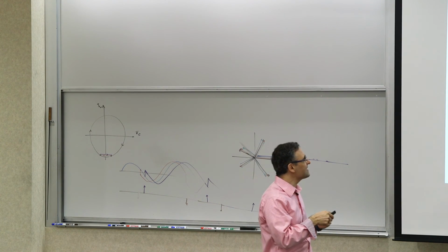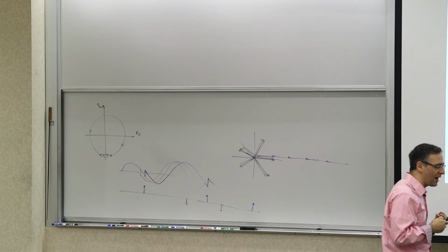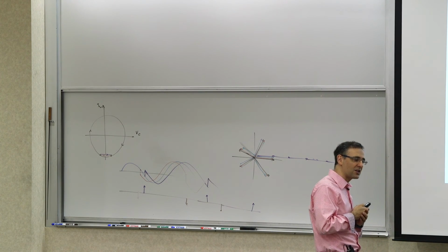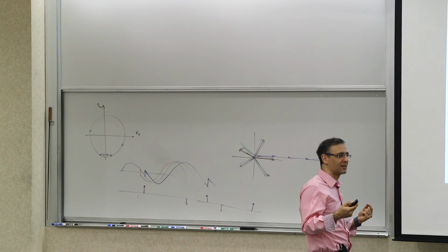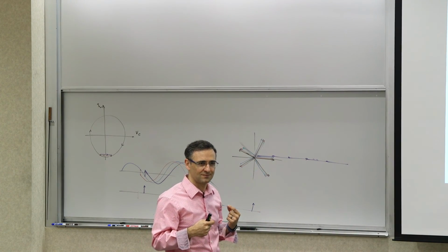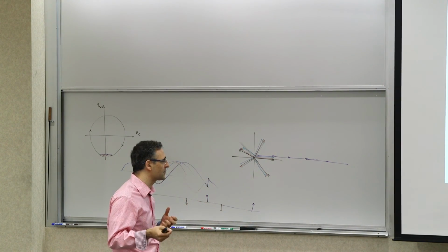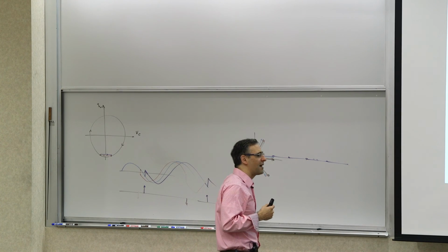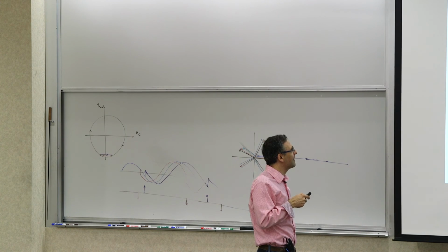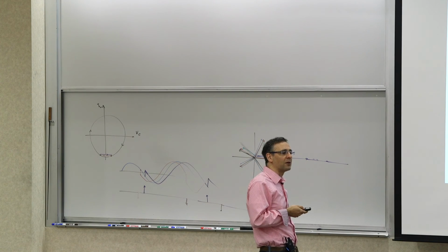So if this is what determines how much the locking range is, you need to ideally optimize the shape of the injection current in such a way that it matches what? So this is a key design question. If you wanted to maximize the locking range, so let's say you're using the locking range for something useful, let's say an injection lock divider or something like that, what does it tell you about the shape of the injection waveform to maximize this product for a given amount of power?